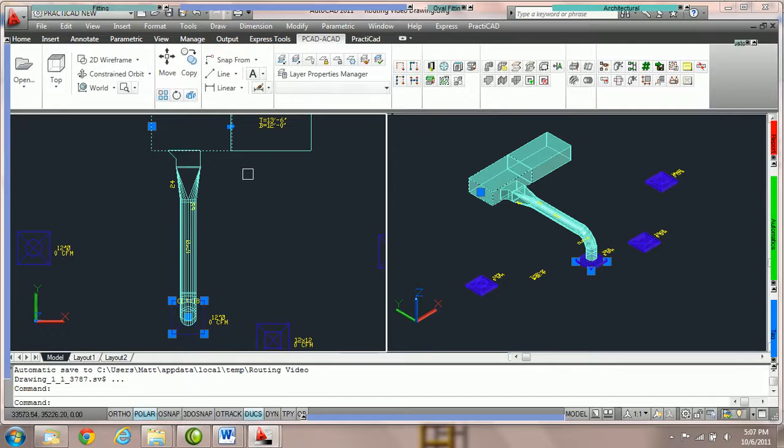When we do that, you can see that PractiCAD has started the route with an angled boot tap. Then it's chosen a square to round at the minimal length, 24 inches. It's switched to spiral pipe, and now it's routed hard duct all the way to the grill. So this is a good way to demonstrate how to use the two round scenario.